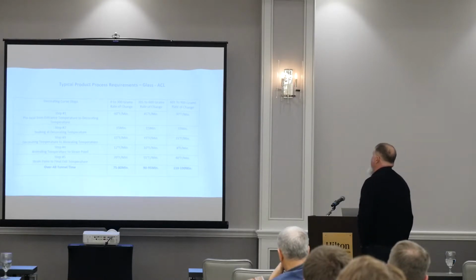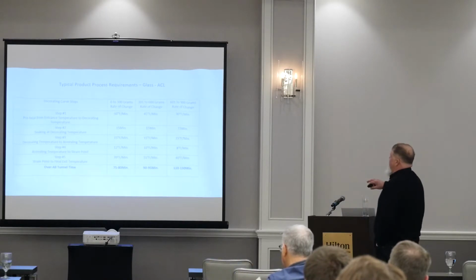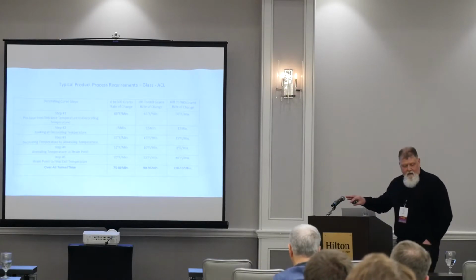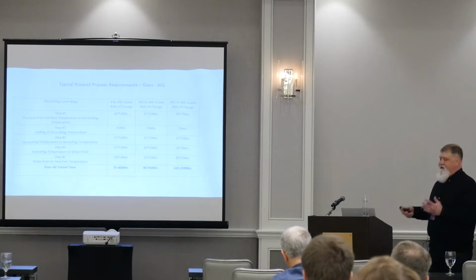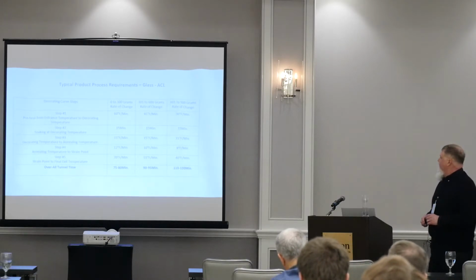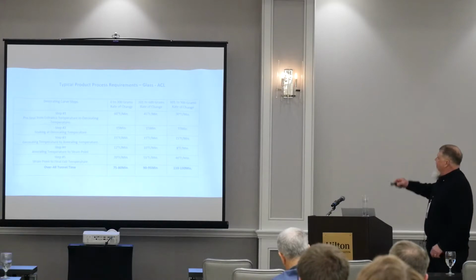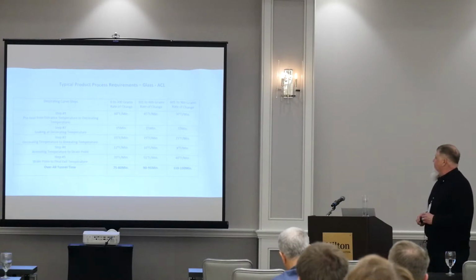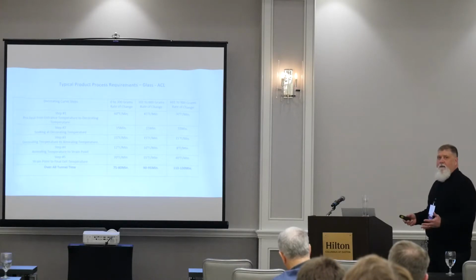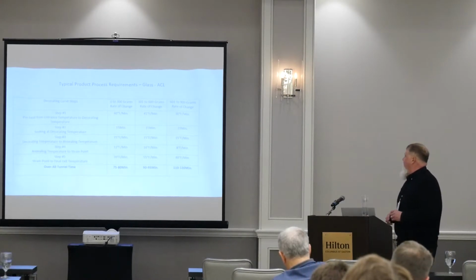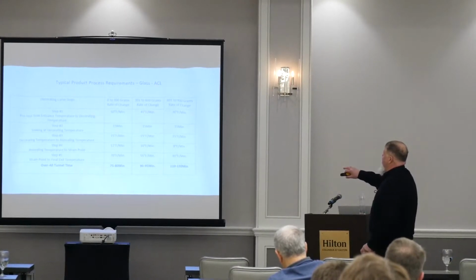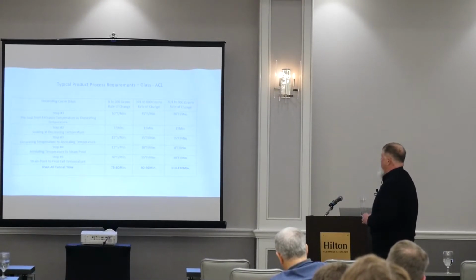Corey was mentioning weight, and I included this as a general rule of thumb. This is for glass, and for a high temperature decoration, an ACL, a label that's going to need 1150, 1180, 1200 degrees to cure. I'm just taking you through the basic steps in setting up a decorating curve, and some correlation as far as glass weight and tunnel time is concerned.